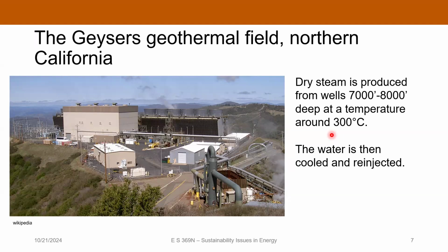because when you cool rocks down, they will contract, right? They get smaller in volume, and that can cause all kinds of adverse things in the subsurface, including induced seismicity if you reactivate faults. And so there's a big thermal management program that you need to have, to make sure that you're not depleting the heat source and thermally shocking the rocks too much when you re-inject those colder fluids. So that's just something you have to be aware of.